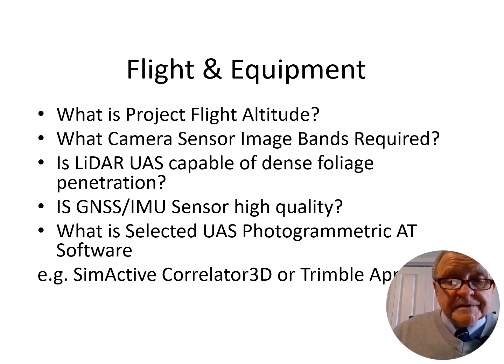Flight and equipment. What is the project flight altitude? What camera sensor image bands are required? Is the LiDAR UAS capable of dense foliage penetration? Is the GNSS/IMU sensor of high quality? What is the selected UAS photogrammetric AT, or aerial triangulation, software? For example, SimActive Correlator3D or Trimble Applanix.